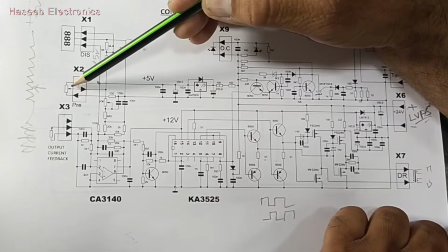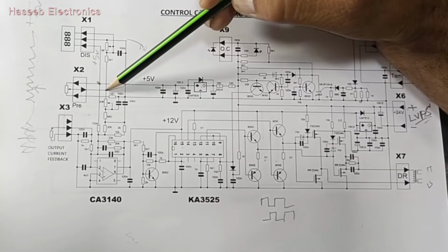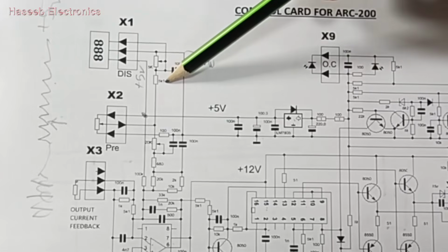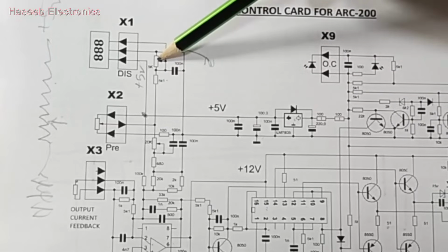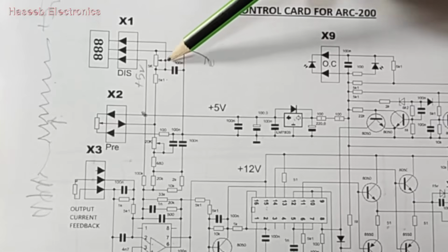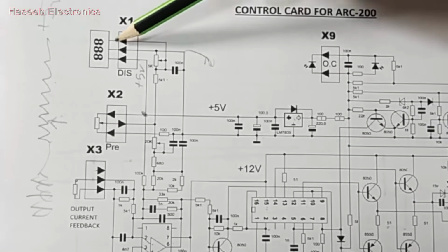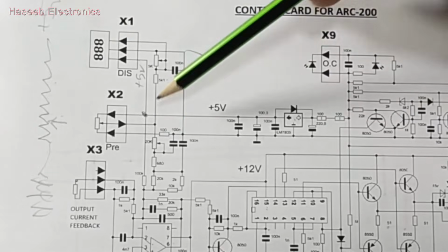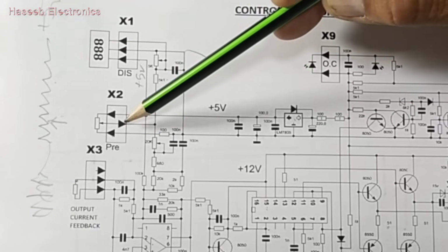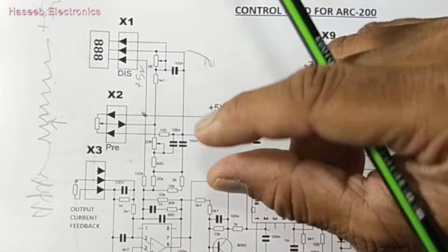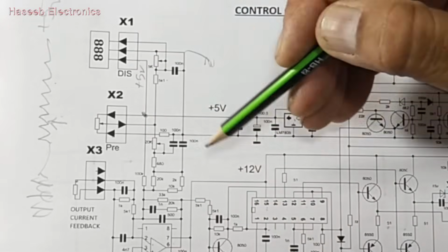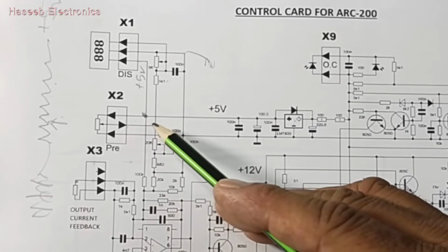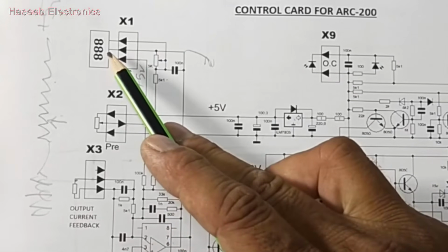If it is closer to ground, less voltage will come in the output, and this voltage is applied to the 5.1k resistor and this 5k potentiometer, and then it is connected to the measurement pin of this display meter. It will display the amount of voltage which we are tapping. Actually we are setting the amount of current, but in the background we are tapping the voltage, and this tapped voltage is sent to this multimeter to display.